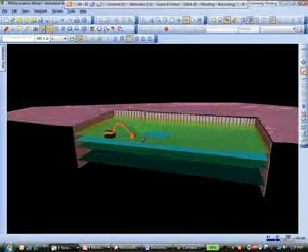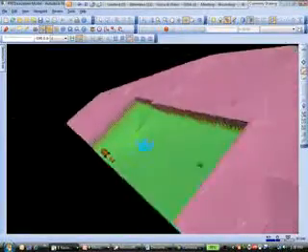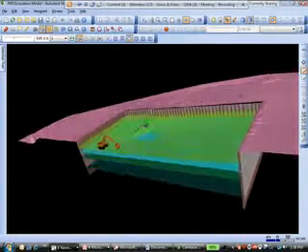So we've talked about some of the different ways we can use laser scan data. They can be useful for bringing additional information into Navisworks, which allows us to work with existing conditions but also incorporate new models on top of that. We also looked at the ability to take these two different mediums and clash them, allowing us to iron out any conflicts between installing the new equipment, or maybe excavation. Utilizing the old and new gives us a true as-built as well as a composite model.